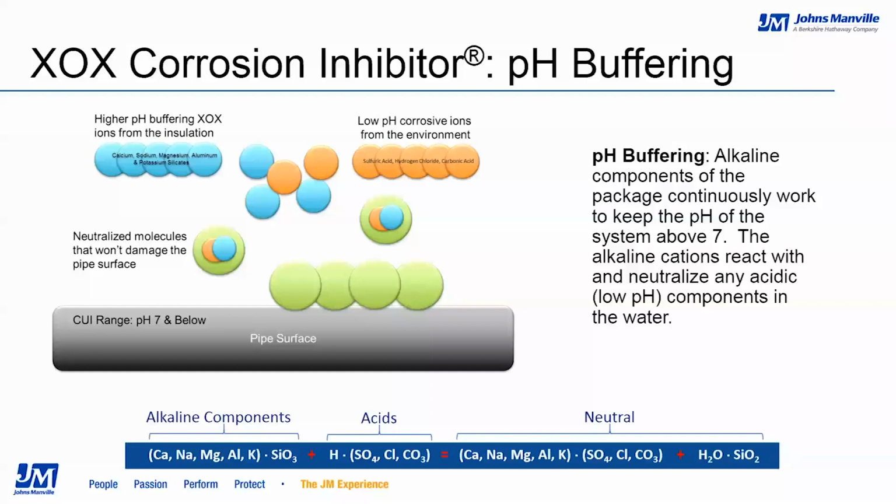In our third-party accelerated corrosion testing, we found that after 6 months of testing, the pH of the insulation next to the pipe surface was approximately 10 for both the Thermo 1200 calcium silicate and Sproul WR 1200 perlite, indicating that it will maintain the pH buffering capacity under severe conditions for the life of the material.